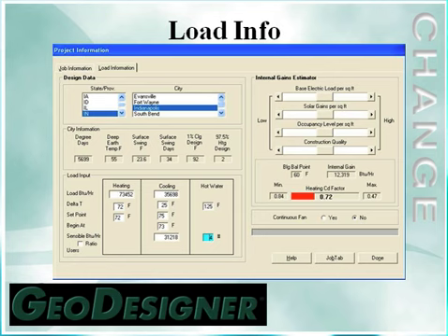One of the other inputs on this screen will be our hot water input. One of the other big benefits with a geothermal heating and cooling system is being able to do a fair amount of the customer's domestic water heating. Normally this has a set point of about 125 or 130 degrees for our water heater tank. And then we need to tell the program how many people are going to use hot water in that building. The program will generate a load, a potable water load, so we can see how much energy we can save on doing their domestic water heating.